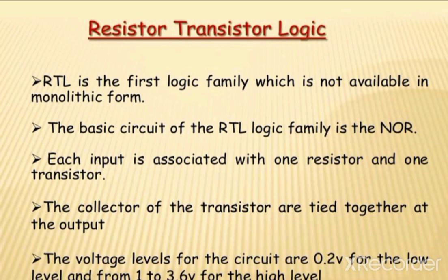So what is the use of this logic in digital ICs? If you go with bipolar logic, then it will produce a high switching speed, and if you use unipolar technology, then it will produce very low speed, right? So if we consider speed, then we will refer to bipolar technology, right?